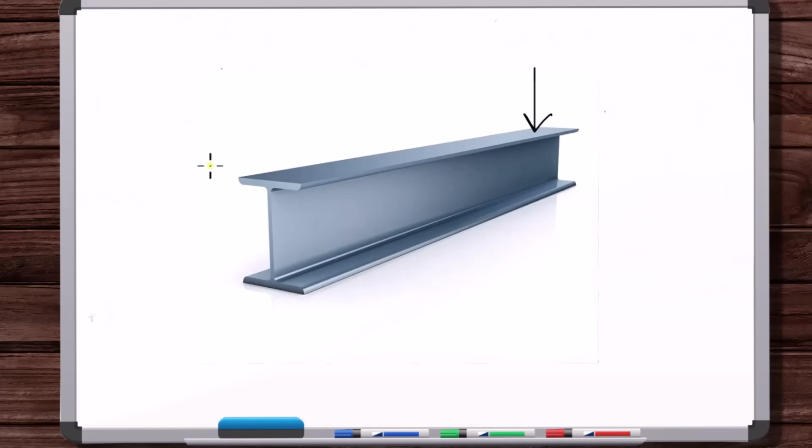But okay, what did we do before? Once we had our component in empty space, we applied all of the body forces. So we can go ahead and apply the weight here. Why not? Maybe it's negligible with beams. Sometimes the loads on the beams are so large, the weight of the beam doesn't matter, but let's apply it. We put it at the center of mass of our cut section, right? It's not the entire beam, just the center of this cut section here. The weight is just the weight of this cut section, just the body that we brought into space.